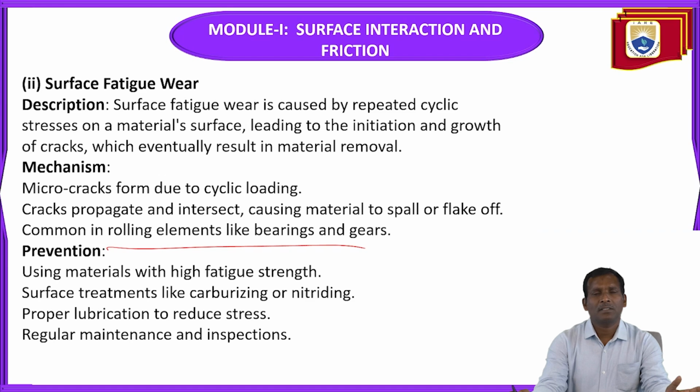So how to prevent this type of wear? Using materials with high fatigue strength and surface treatments like carburizing or nitriding. Proper lubrication to reduce stress. Regular maintenance and inspections.